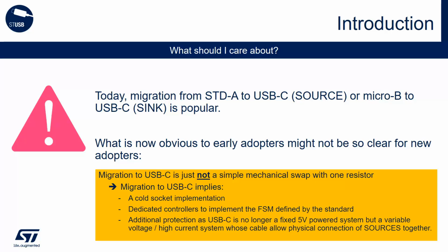So we need to consider protecting by default every USB-C port to 20-volt shorts or more, even if the application is only for 5 volt, since not only 5 volt can be available, since voltage is scalable.